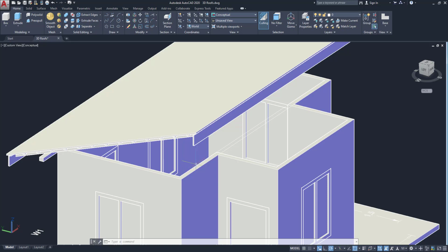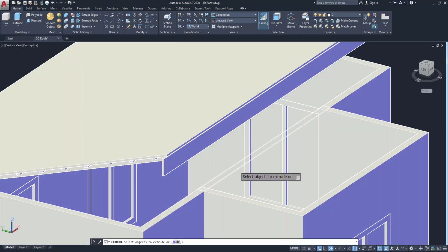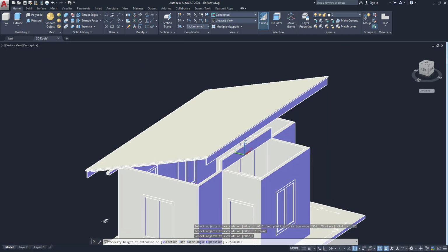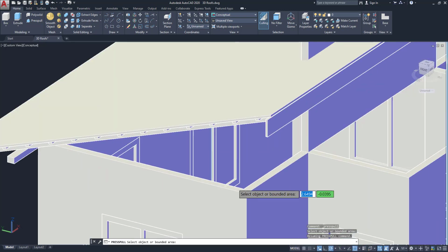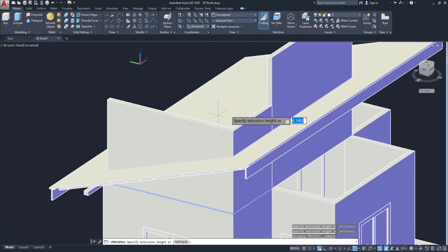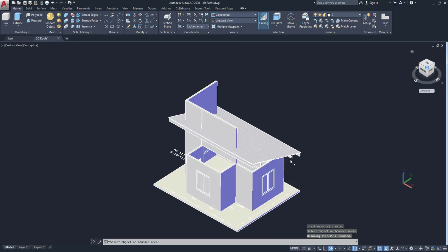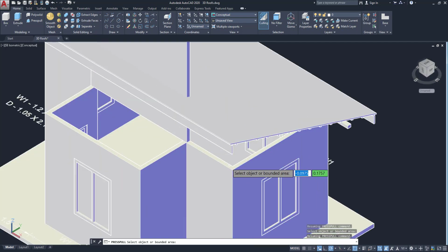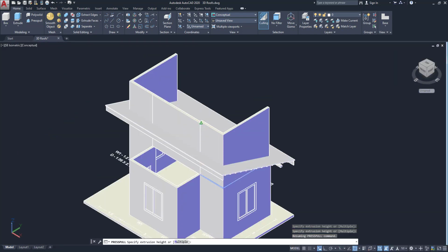First I have to complete this larger part. So here I have to complete this one. Before, you can use the extrude and go to here and extrude this one above this line, and same as here, click on this brush tool and go here and select those areas and you can extrude it up to here, same as the other side. Go here and extrude this part up to here.